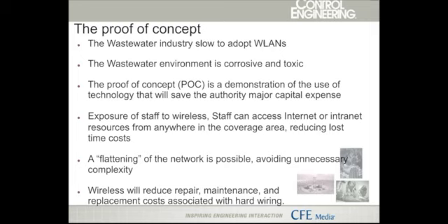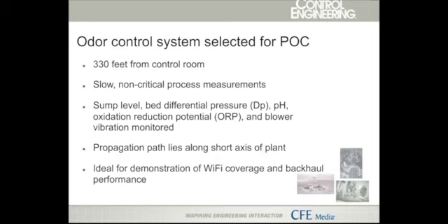We wanted to flatten the network. We didn't want to have a hierarchical system of networks layered on top of other networks. We wanted to have a flat network throughout so that anyone on any network segment could access process data. And obviously, cost, a major factor in municipal environments and decision making. So wireless will reduce the repair, maintenance, and replacement costs associated with hard wiring.